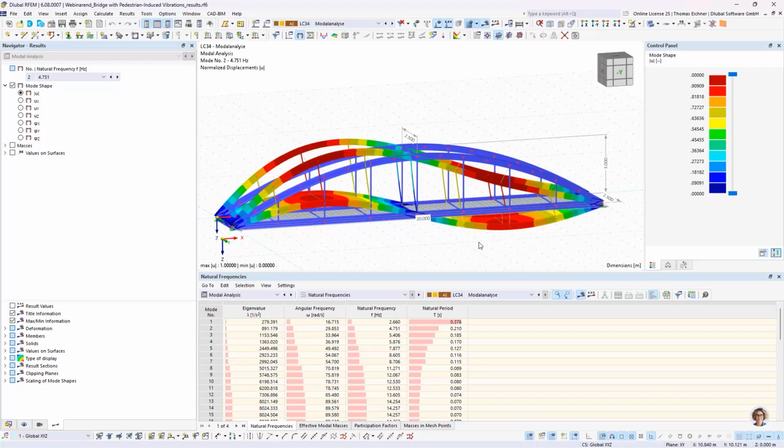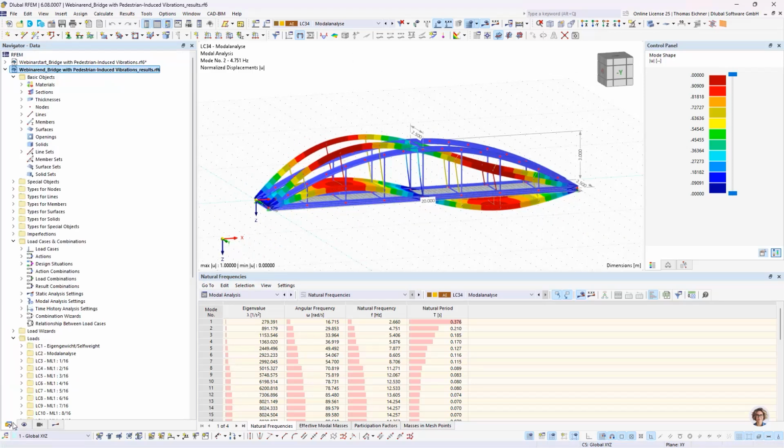So if you just do multiple time history analyses, the time won't increase too much, and in the end, you have different results on different investigations on the structure. You could use structure modifications where you increase the stiffness, for example, of all of those HEB, and so on. So think about what you are interested in, what influence of some changes in the model you are interested in, and define that before the first calculation, and just go for 4 time history analyses with different structure modifications at the same time without losing too much calculation time. That's another tip there.